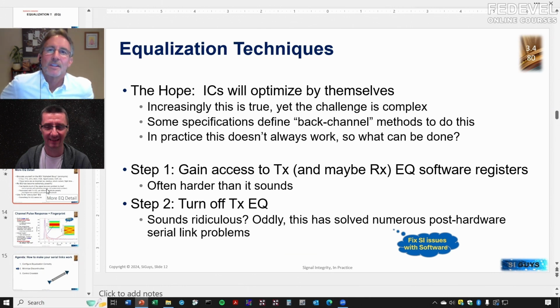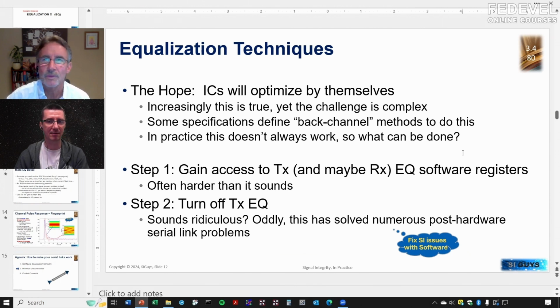And again, registers, right? It will tell you that, and certainly a protocol analyzer, which a lot of times in the lab, bringing up these things, you'll hook up a protocol analyzer that's watching all the traffic, and that will tell you, oh, we made it to Gen 4, we made it to Gen 5. Make sense? I thought there is some kind of test software, but probably once it is set up and working properly, you can read from a register what speed or generation it is running on. Right.